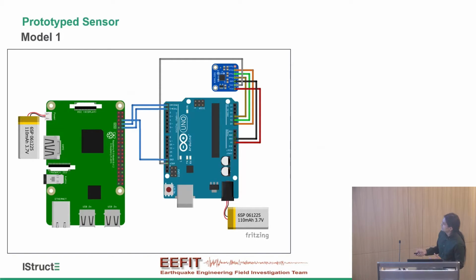So this is the sensor, one of the sensors actually that we've been testing. To give you an idea, it's a low-cost sensor that has mostly 3 or 4 parts, the main part being this board. This is basically a tiny computer. You can see the peripherals here. Those are USB ports. This is an Ethernet cable for sharing information, communications. Then you have this open hardware called Arduino Uno, which is actually our digitizer, the one that is collecting the data from our micro electromechanical sensor.